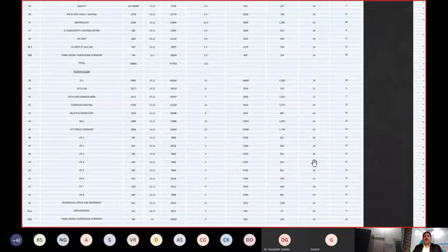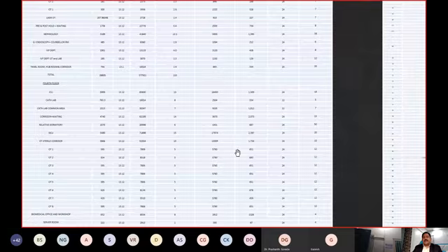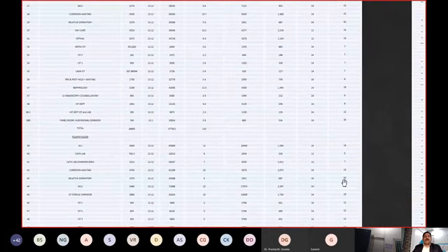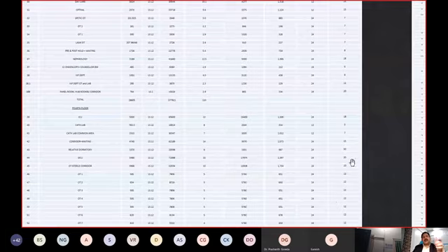Now we have to see what the CFM is, what the fresh air is that we are going to consider, what the air changes are, what we need to do, and how many people will be inside the OT. These things are very, very important before designing, and only this will give you the proper result. If a mistake happens, then every time you have to suffer with this energy calculation.